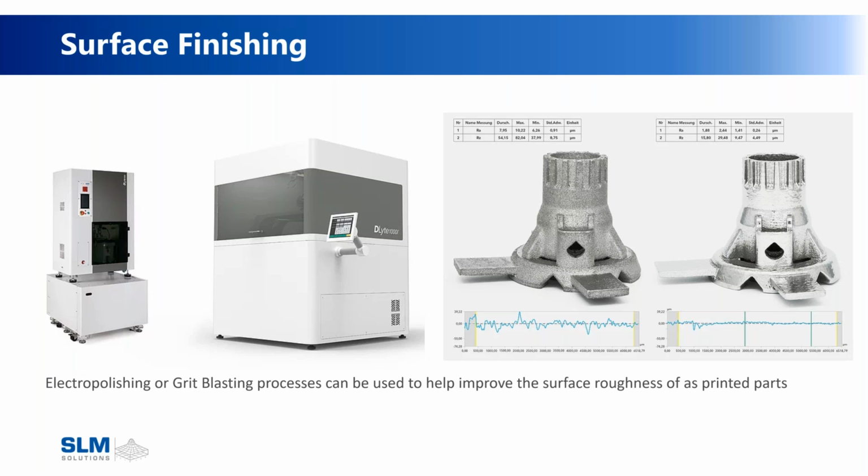While we're looking at this part, a few of the things that we'll notice is that those holes aren't round. For design, that hole was designed in a teardrop fashion. The reason that's done is that hole can now be printed support free, because as that hole closes up, there's no support needed because we never reach an over 45-degree overhang. So that's a design element that was designed specifically for the additive process.